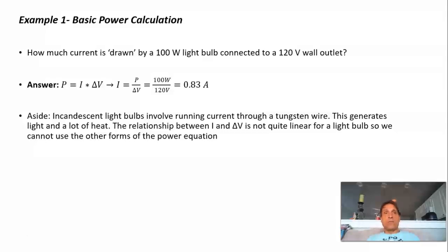So that's why sometimes if you have the microwave running and the stove on and the fans on and maybe one or two other things, your breaker will trip and everything will turn off, okay? Because the currents are adding up to more than what the breaker is rated for. It's rated to trip at 15 to 20 amps. So it's important to be able to do these quick calculations relating current, power, and voltage.